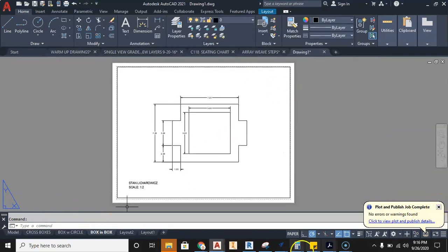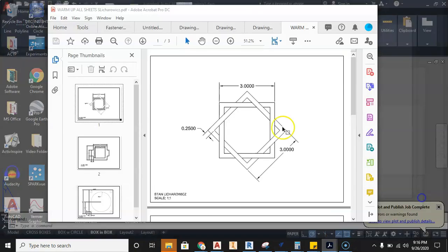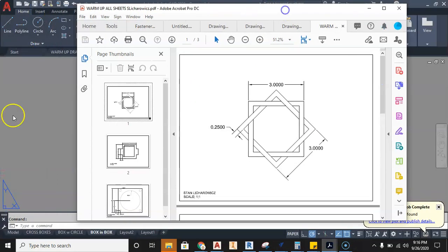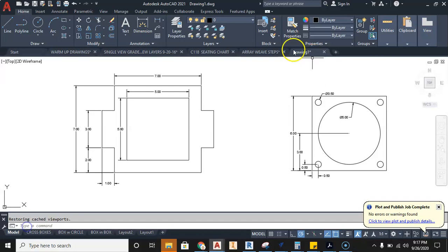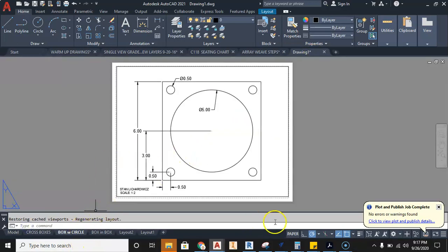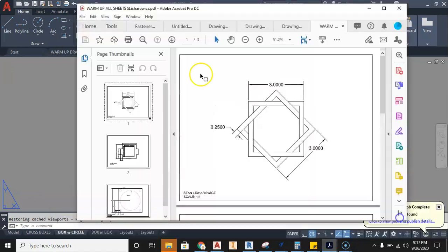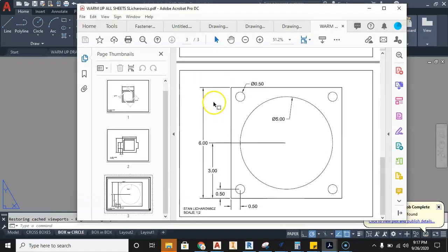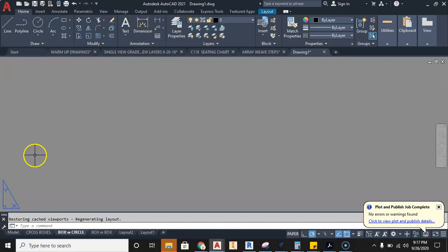And now I'm ready to go and submit this to the assignment. All right, so I hope this helps work you through the process step by step, how to get from your drawings here in model space to your layout space, then to PDF, and then how to bind your PDFs together, and then submit these to Canvas. All right, hope that helps out.